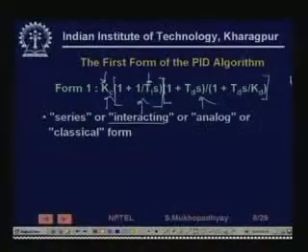If you change Ti also they will change, if you change Td also they will change, and then all of them will change. So, you see that they interact, that is you cannot independently, unless you do it very carefully by actually solving equations. If you just change Ti, then it is not just that the integral time is going to change, the derivative time will also change and the proportional gain will also change. So, therefore, the changes are interacting with one another, and that is why it is called an interacting controller.